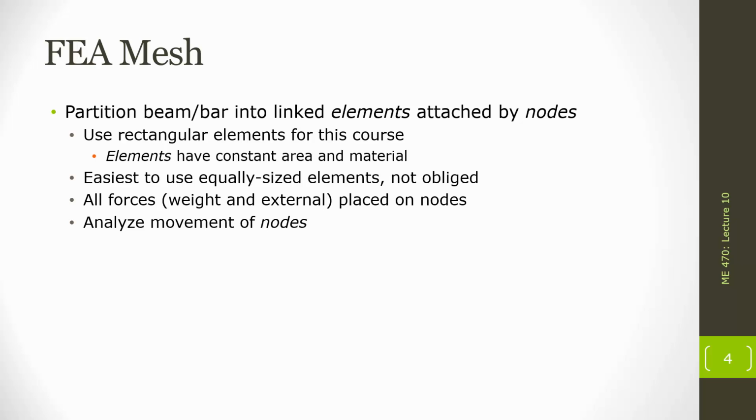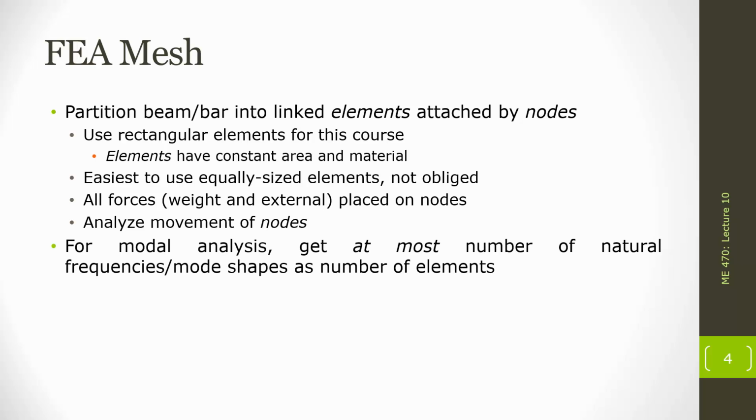And what we're going to be focusing on is really what we call modal analysis. We're going to have some bar, some beam with a more complicated geometry than we would be able to analyze using the continuous approach, the partial differential equation approach. And we're going to still be interested, though, in finding out what are the natural frequencies and the mode shapes of these more complicated geometries.